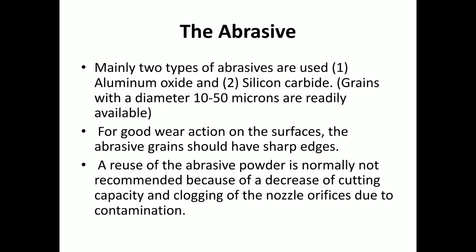Reuse of abrasive powder is normally not recommended because of decrease of cutting capacity and clogging of the nozzle orifice due to contamination. Once the abrasives have been used, they cannot be reused because they lose their cutting edge, so they have lower cutting capacity.